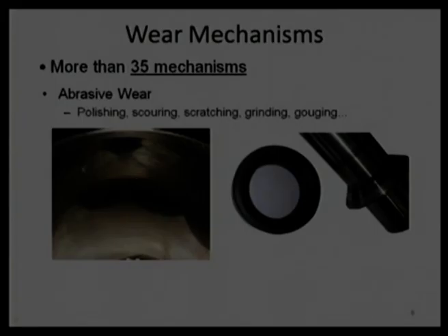If the surface is textured to retain the lubricant, the texture will be removed, and if that texture is getting removed, we are losing performance. If I say some sort of diamond shape given to the liner to retain the lubricant, as a storage purpose, and if those diamond shapes are getting polished, naturally that performance will come down.